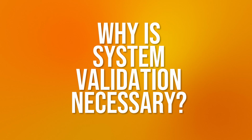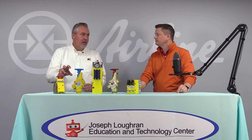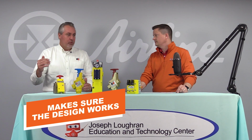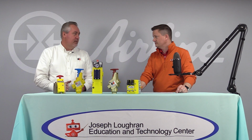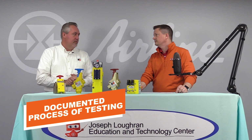The topic that never seems to really get discussed a lot is the validation of it. Why is a validation of the system necessary? Well, the validation is the testing process that makes sure that what you identified in the risk assessment and the mitigation solution you selected actually works. And does it work in the right modes as designed? So this whole thing about verification and validation is all about proving that it did what you intended it to do. And so that's a documented process of testing.